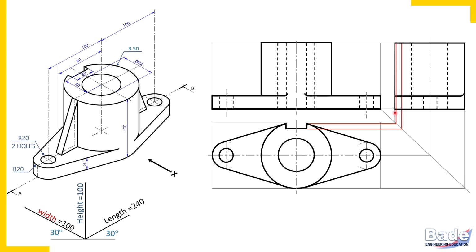Now, as I told you, the boundary generator is no more there, that is to be erased. So I have erased it. And this rectangular slot, watch here, this is a rectangular slot here. You never draw a hidden line at the boundary, remember. So this is a boundary edge of the slot, and hidden edges of the slot. So this is how we have completed the slot in all three views.